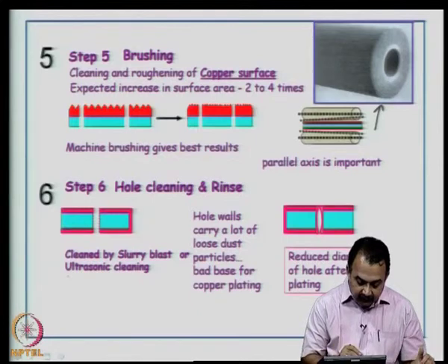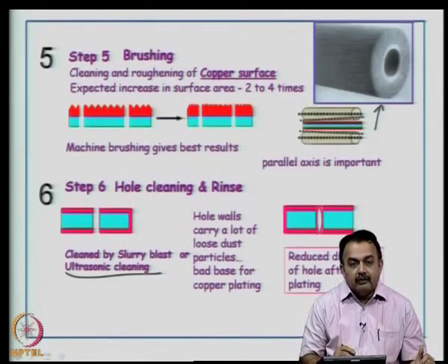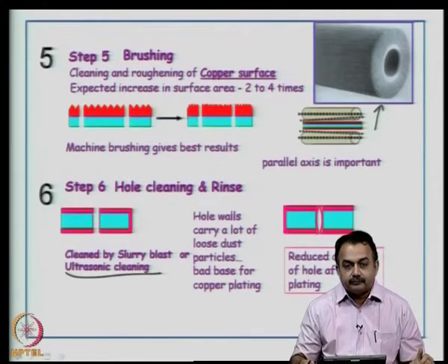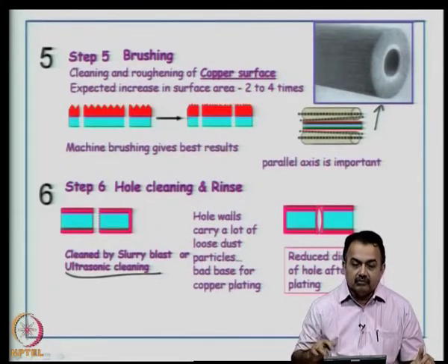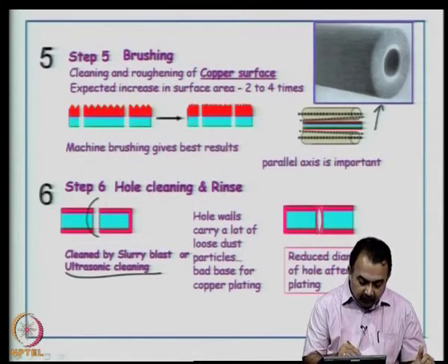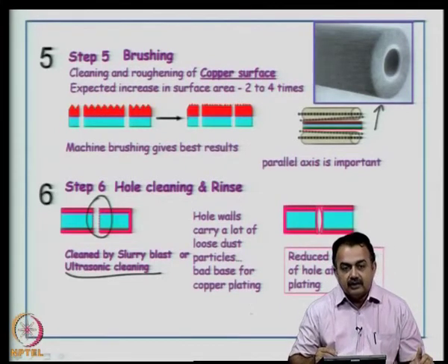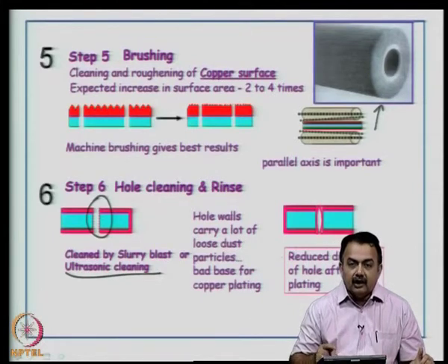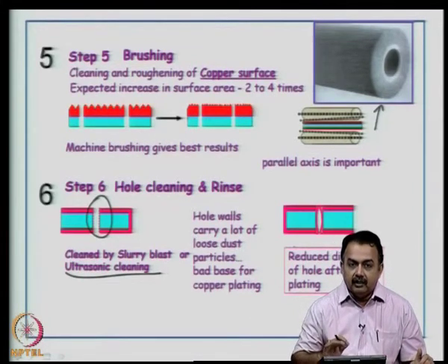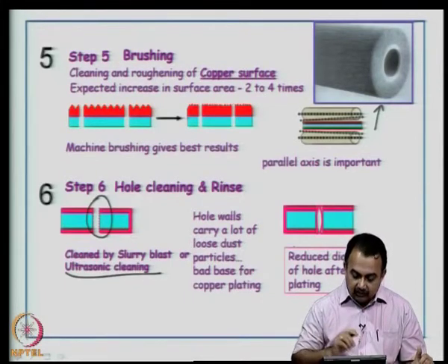So, as I said, you can use ultrasonic cleaning, where you can use a mild acid, or you can combine both mechanical brushing and chemical cleaning to make sure that the hole wall is perfectly cylindrical and devoid of all debris, glass fiber, epoxy smear and so on.